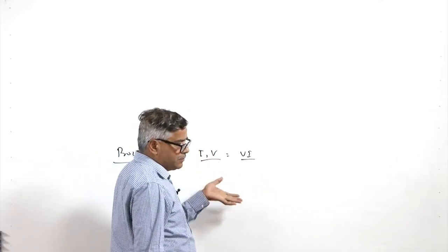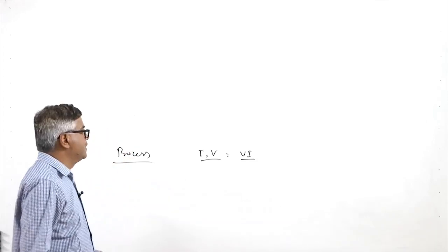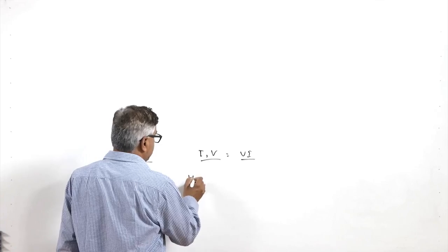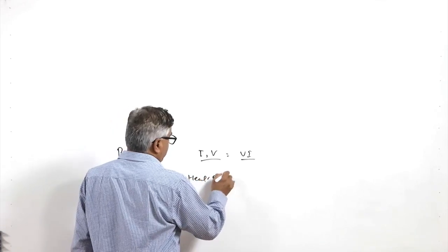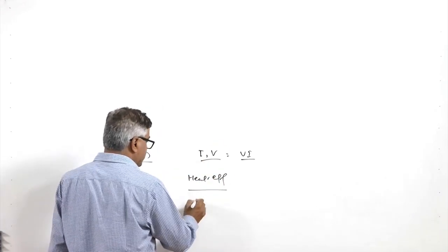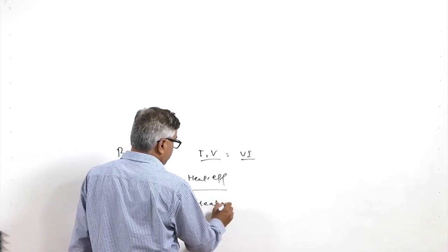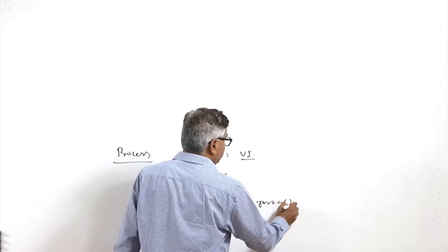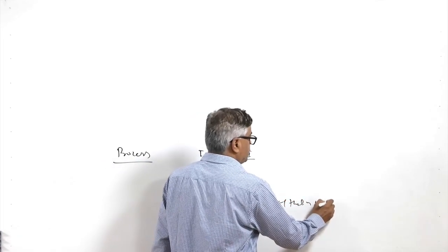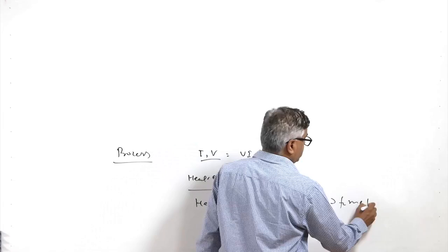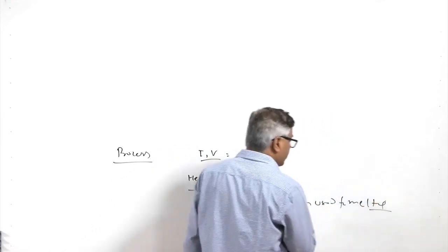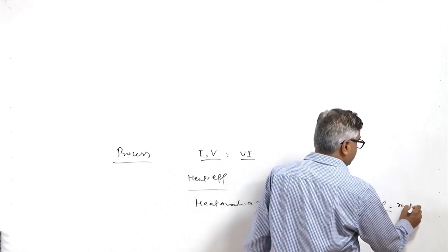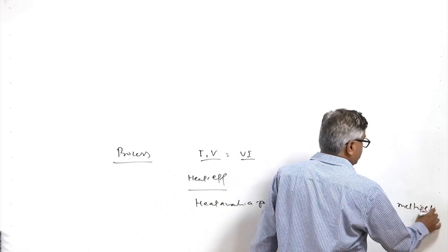The part of the energy which is converted into heat is termed as the heat efficiency. Of the heat available, only a part is used for the melting. The portion of the available heat that is used for melting gives us the melting efficiency.